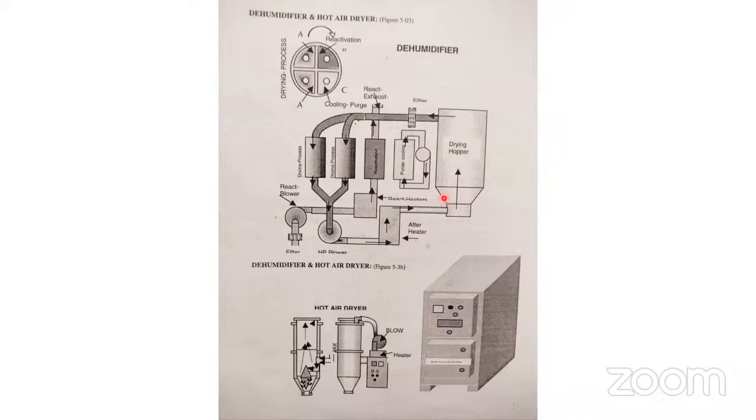Therefore, by using a dehumidifier for this material before adding it in the hopper of the machine, they absorb all the moisture from the ABS, nylon. This is a dehumidifier here, friend. It has four compartments. The material goes through each compartment. Each compartment has a function to remove the water from the plastic granules. And you will get a dry material from this dehumidifier.